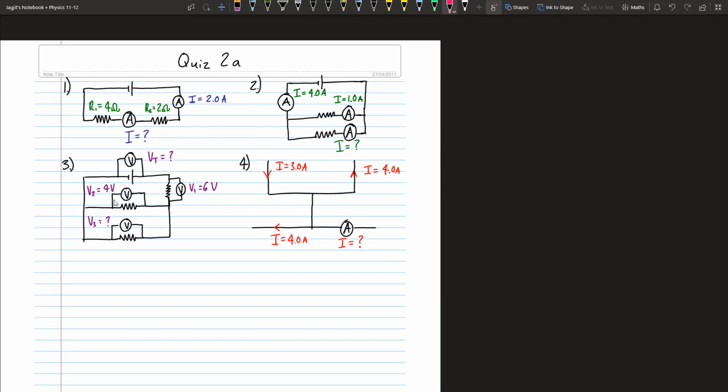Well, they're telling you that the voltage drop, you see, this is going to measure the voltage drop across this resistor. It's 4 volts. And they're saying, what's the voltage drop across this? Well, guess what? These two resistors are in parallel. So whatever the voltage drop across these 2 points is, nothing is in here in the path. So the same voltage drop is going to be across these 2 points. If this is 4 volts, this will be 4 volts too.